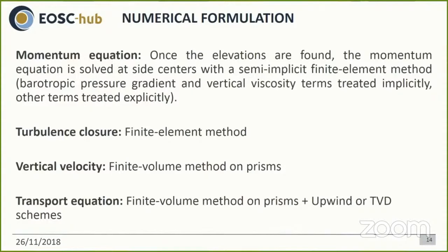Once the elevations are found, the momentum equation is solved at side centers with a semi-implicit finite element method. The turbulence closure is treated with a finite element method too. The vertical velocity is treated with a finite volume method on prisms, like the transport equation. The latter is then solved with upwind or TVD schemes, which won't be detailed in this course.